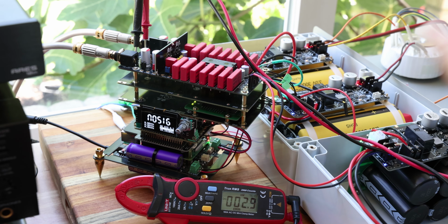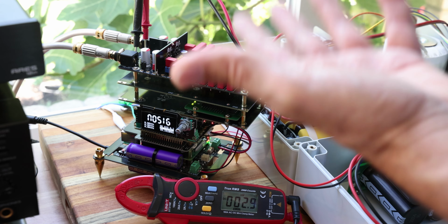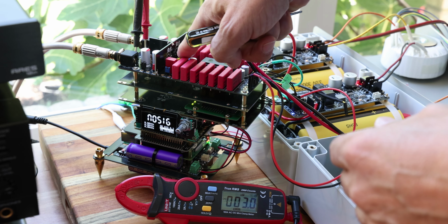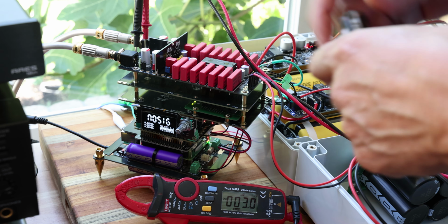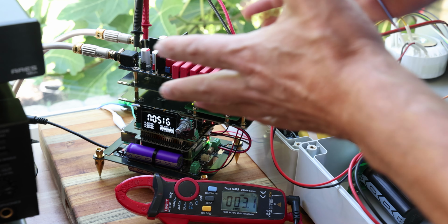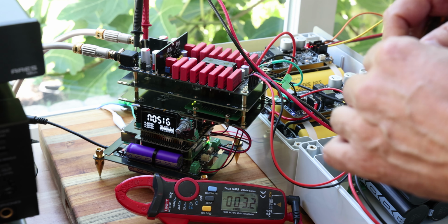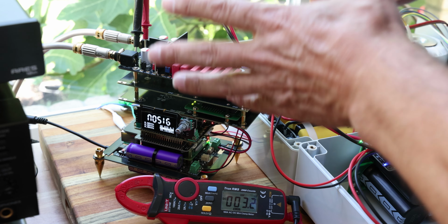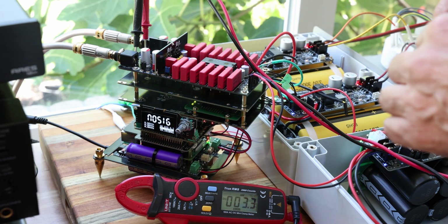And like I said, everybody can do things differently. If someone wants to put capacitors, they can put capacitors. You simply take those jumpers out, and now you have no more DC offset. You use your capacitors, and you're good to go as well. So you have options. This board can be configured in any way you like. You don't have to use it the way I have it set up, but this is my preferred configuration, and that's where I think all the magic is happening.